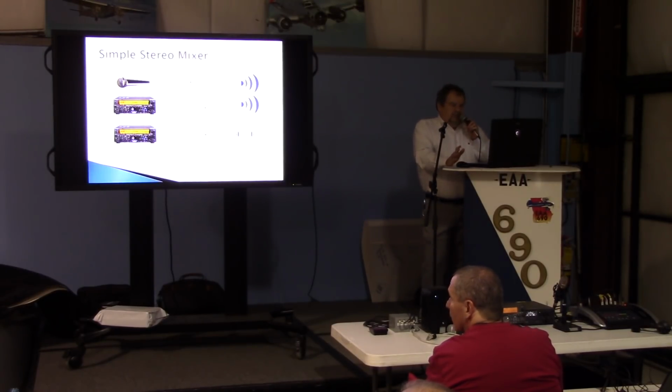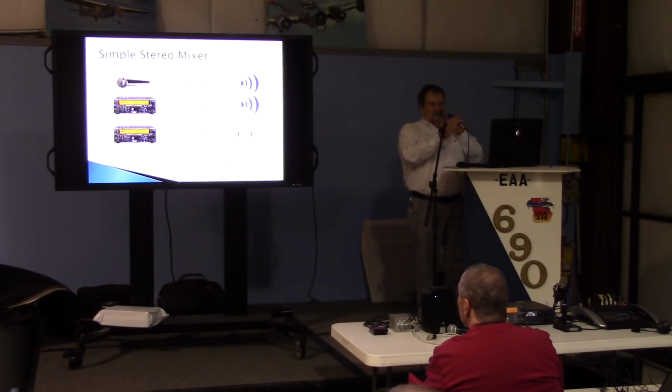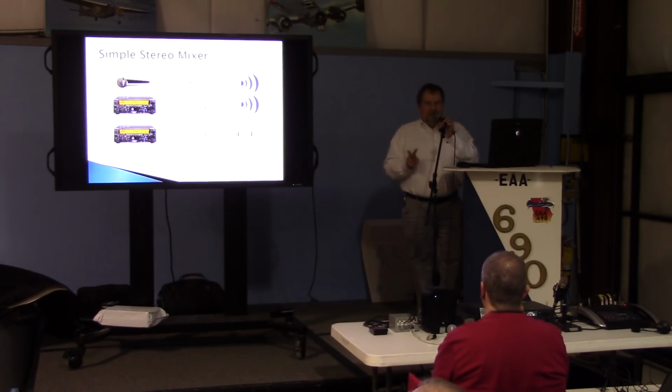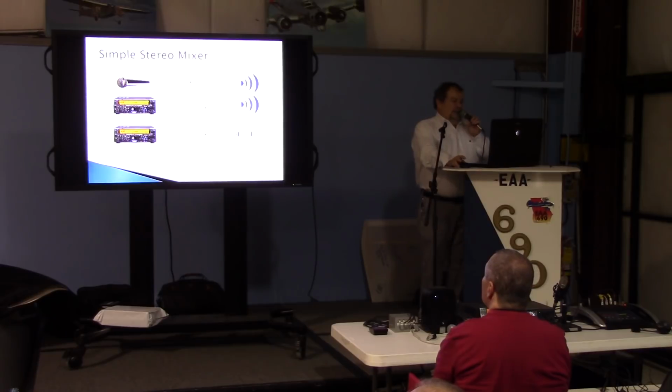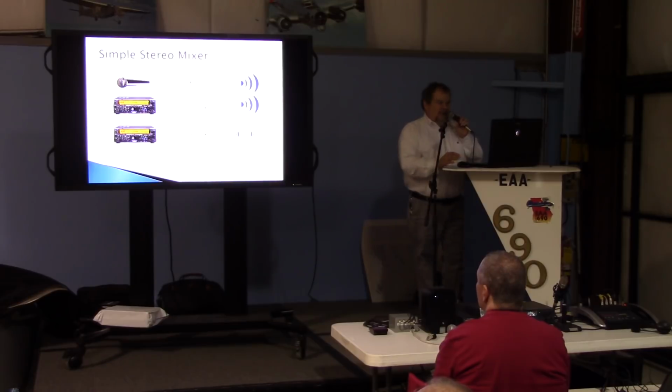Here's a simple stereo mixer. It's got 2 channels, left and right. Or in some circles we call them buses, but this would be considered a single bus mixer, because when you say bus in the audio world, you generally always mean it's a stereo bus. It's got 2 channels. And so you can see we got the mic connected to the left side, and it's feeding this radio, and it's feeding that radio. And we only have the mic set to come out of the left channel.